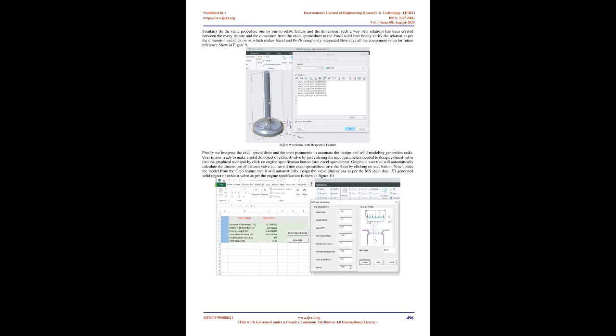3.5 Assigning data with part feature. To relate the Excel spreadsheet data and the Creo solid part feature data, a special command exists in the Model option from the Intent menu, called Relations. Select the Relations button. The Relations dialog box will open; select the feature from the model tree. As soon as we select the feature, its relative dimensions will flash, as shown in figure 7.